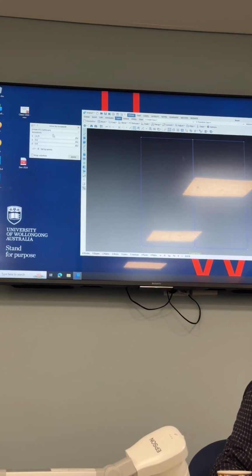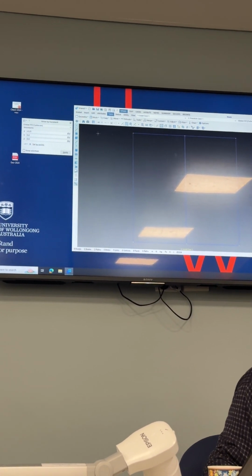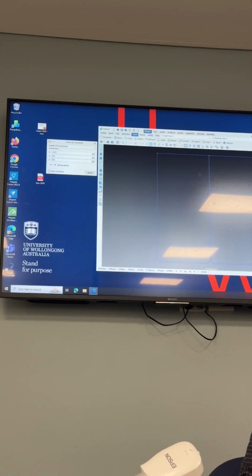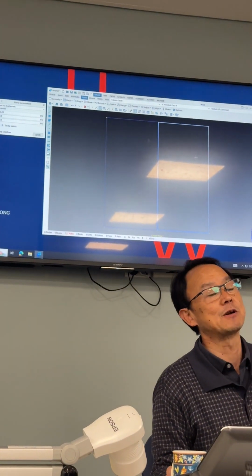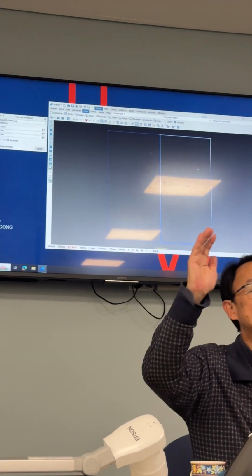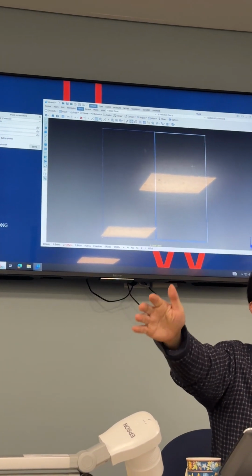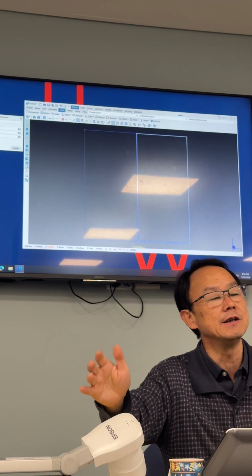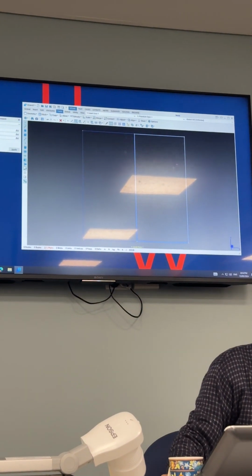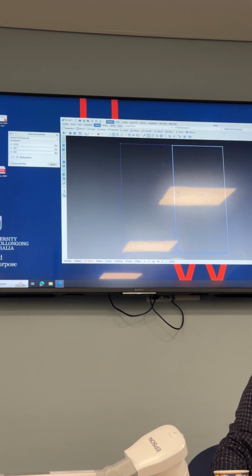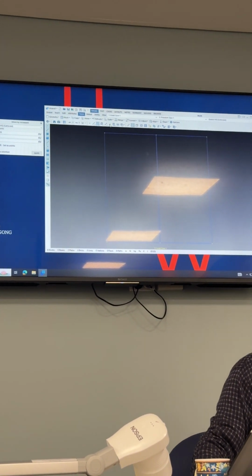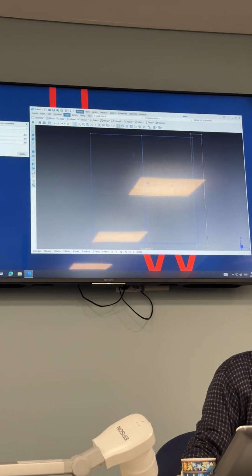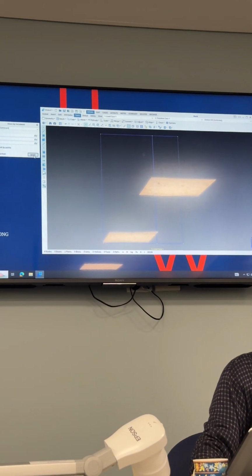After I define the movement, I'm going to choose the point to be moved. So I choose these 2 points, move it. If I choose the element, I'm going to move the element. I don't want to move the element, I only want to move the points. Then I choose the nodal points only. So you undo it, and you choose the points. Okay, that's what you got.